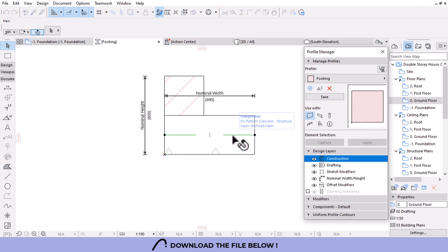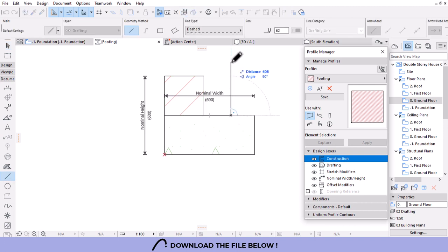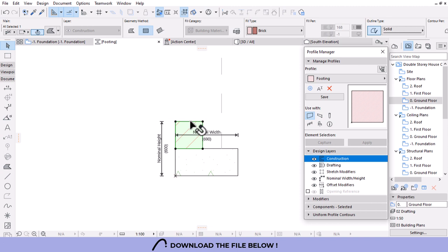Perfect. So I can get rid of this line as a guide. And then the brick wall. So this is the footing. This is going to be a brick wall. Let me just draw the height of the brick wall, because the height of our foundation or depth of trenches is 1 meter. So I'll say 1000, which is 1 meter, and then stretch this to there.